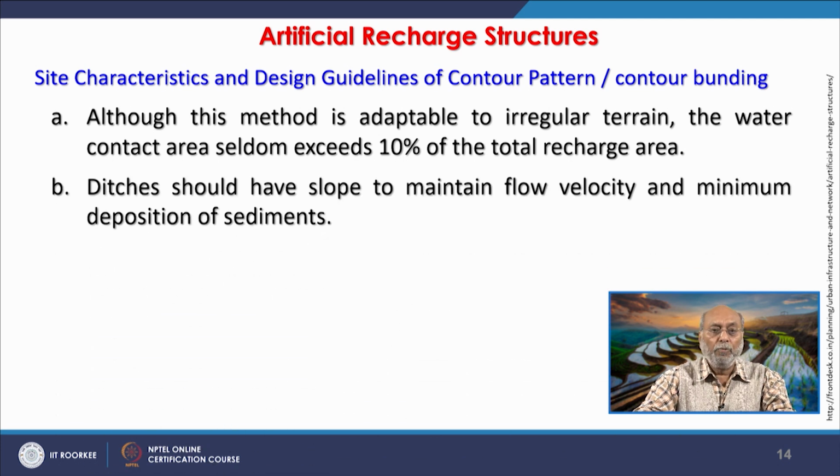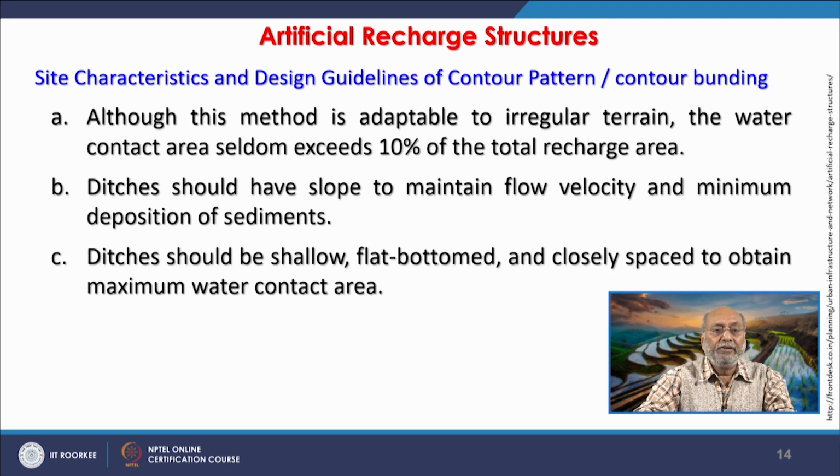Ditches should have a slope to maintain flow velocity and minimum deposition of sediments, and ditches should be shallow, flat-bottomed and closely spaced. Why flat bottom? So that we provide the maximum area for groundwater recharge or infiltration, and closely spaced to obtain as much water contact area as can be made.